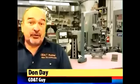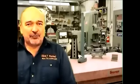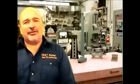The April 2012 through June 2012 tips explain the meaning of 2, 3, and 4 segment composite position tolerances. A composite tolerance has one geometric characteristic symbol but multiple segments. These next 3 tips will show sample gauging that could be used to inspect those composite tolerances. I do not want to suggest that gauging is the only way to inspect composite tolerancing. Some high-end CMM and vision system software can handle composite tolerancing.